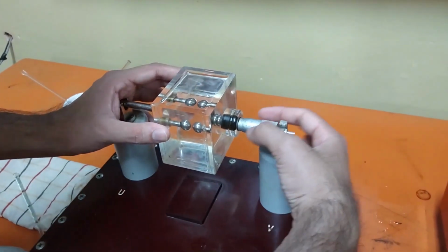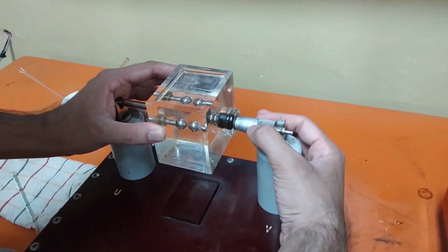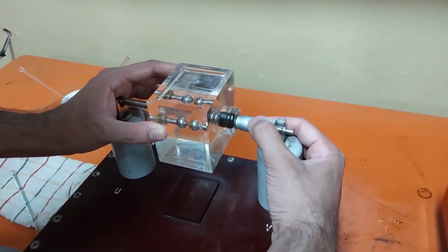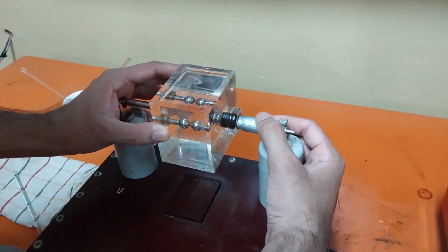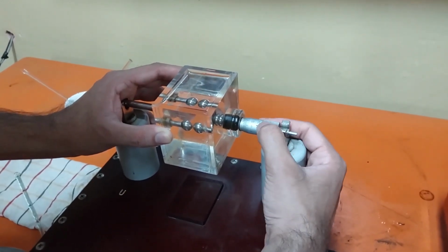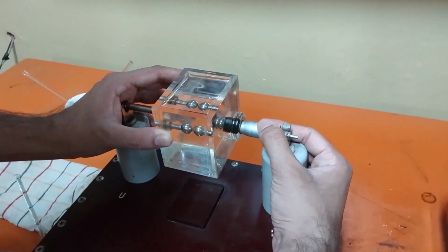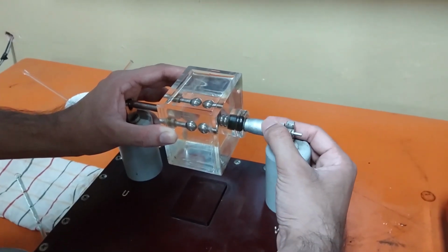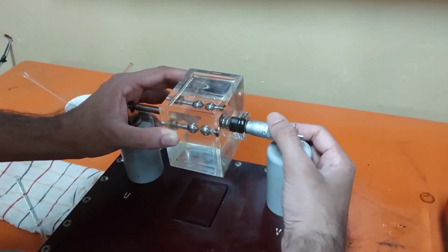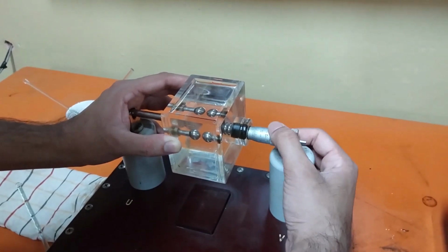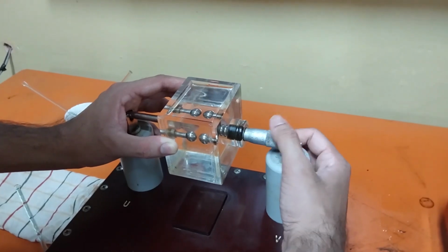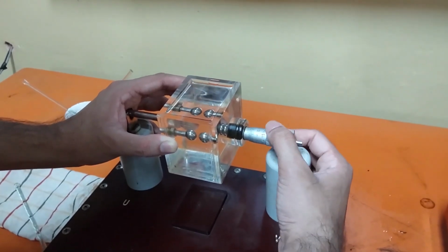But keep in mind that we have to repeat this test for gap spacings from 1.5 mm to 3.5 mm in 0.5 mm steps. After fixing the container properly, please make sure to remove gas bubbles or solid particles if there are any. We'll show you how it is done in the upcoming part of the video.